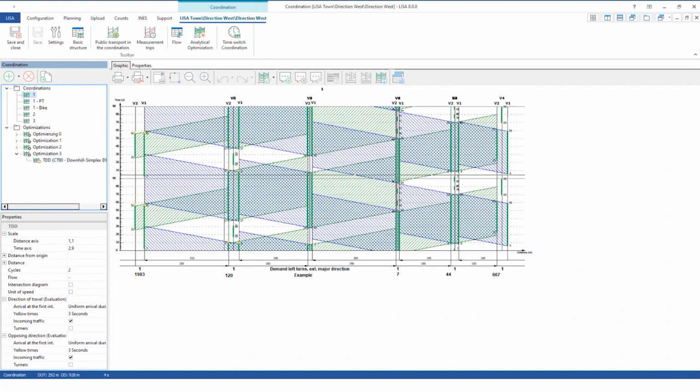So this is a time distance diagram of the loaded intersections. Before, I have given the information like what are the distances between the stop lines. This is information that you can probably get from Google, measure it from there and put it in here, or you have exact measurements. If your measurements are not accurate to the meter, that's not so important. It should be accurate to like 5 meters. I think that's where you can still get pretty good results, because we're usually talking about progression speed of 15, 13, 14 meters per second. So the resolution should be high enough so that it makes sense.